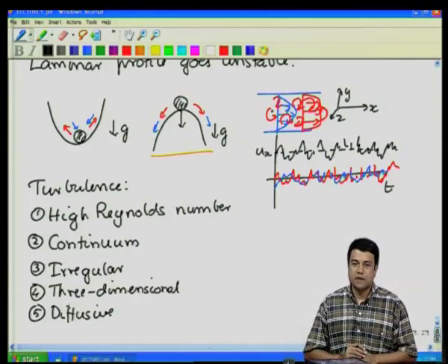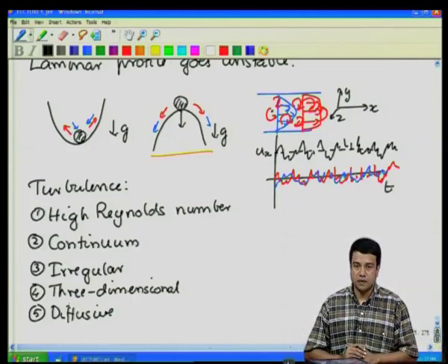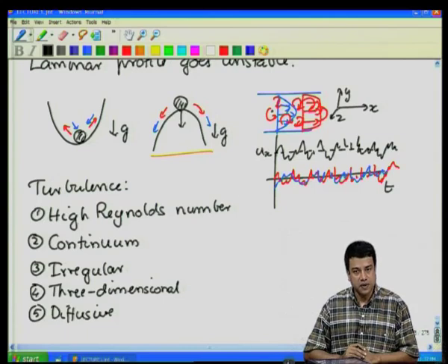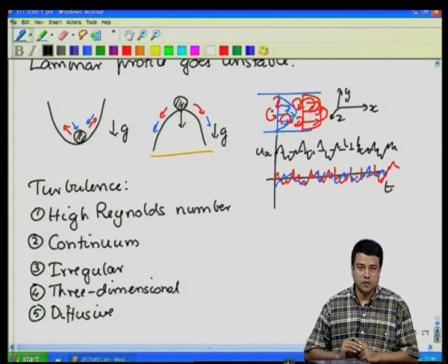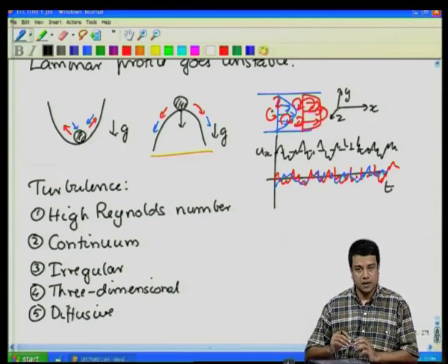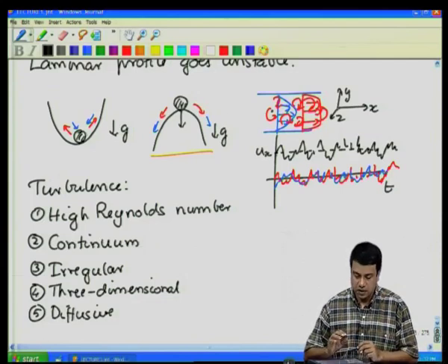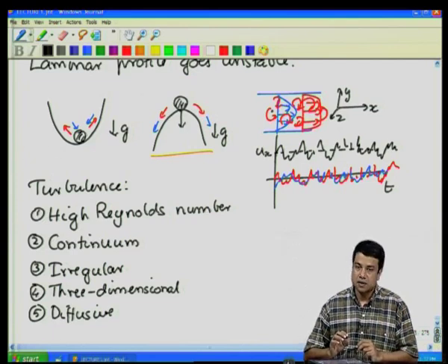The diffusion coefficient in a turbulent flow is often orders of magnitude larger than that in a laminar flow. The reason for that is the mixing that takes place due to the transport by these eddies, these parcels of fluid. Formally, an eddy is defined as a parcel of fluid in correlated motion. These little packets of fluid, as I said, have velocities in all 3 directions, so they are moving both streamwise and cross stream.